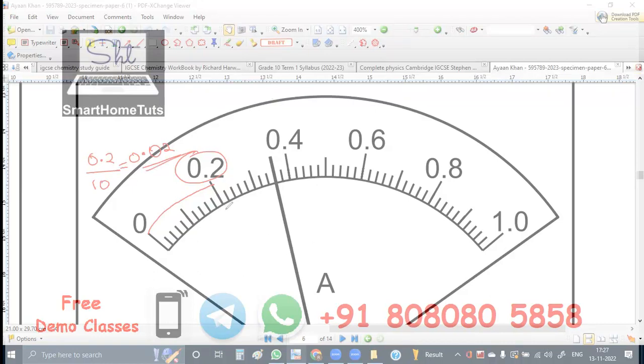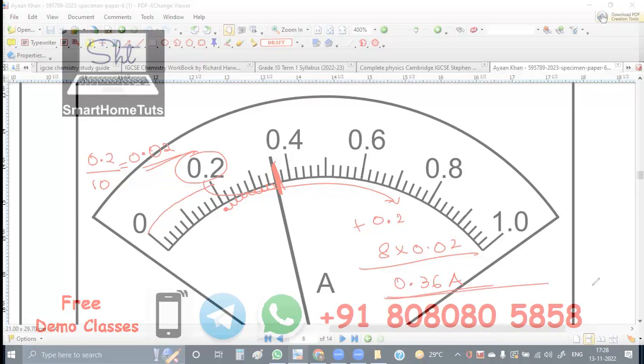Now from 0.2, from this point I count how many steps are there? 1, 2, 3, 4, 5, 6, 7, 8. I'm reaching up till the pointer on the 8th step. So 8 multiplied by 0.02, plus the original 0.2 is also there. If I'm adding this, I'm getting 0.36 amperes. I've explained to you twice. Go through this recorded video very carefully.